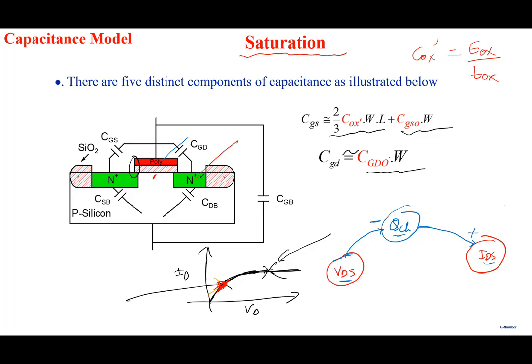Drift velocity. So yes, VDS increase, if you would like, is causing an increase in electric field, right? In the channel. So you'll say plus. And electric field is causing, as he says, plus drift velocity of electrons, and this is causing a plus higher current, drift current. Correct? So now you have another path.